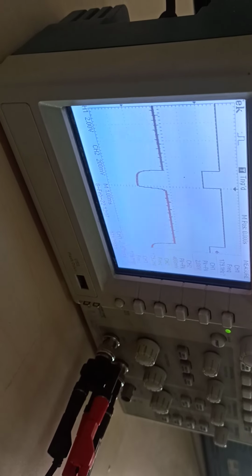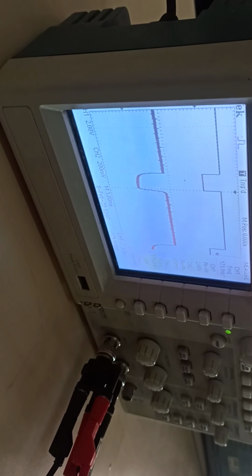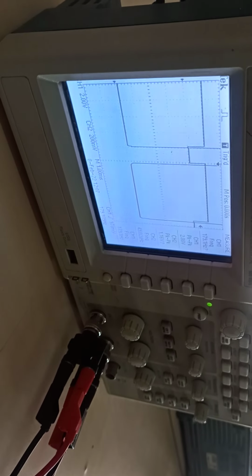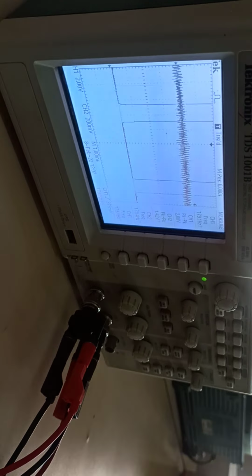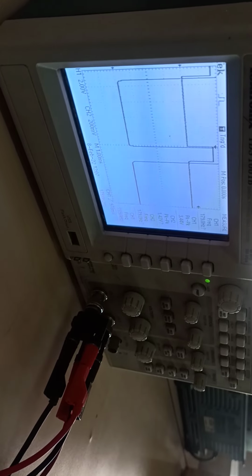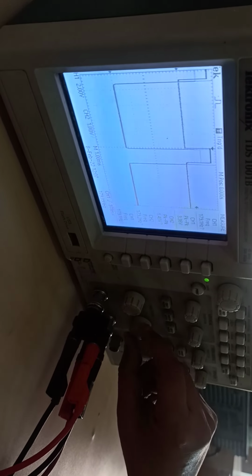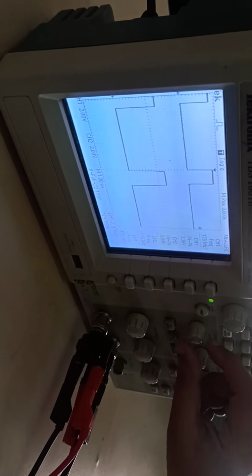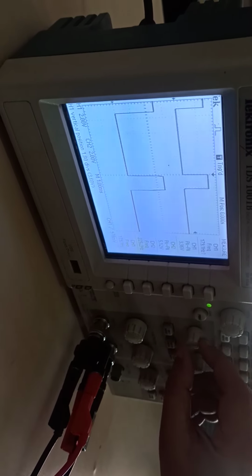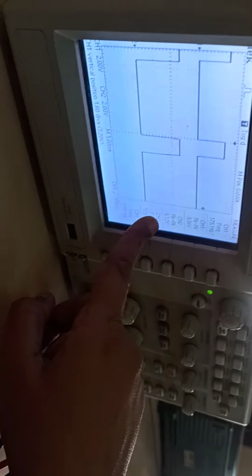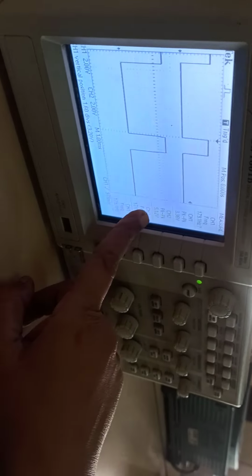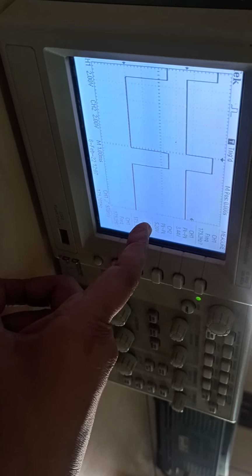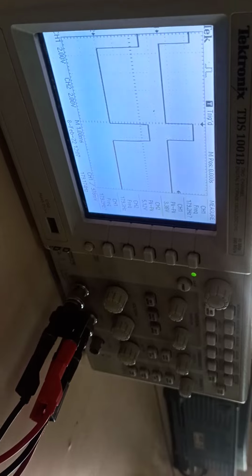Okay. Now I am connecting on the output side. On the output side, channel 1, I am going to connect again to the pattern. So channel 1 is connected to the pattern. See, whatever input we have transmitted, that we are going to get on the output side with the amplification. So channel 1 3.34 millivolts and 5.2 volts on the output side.